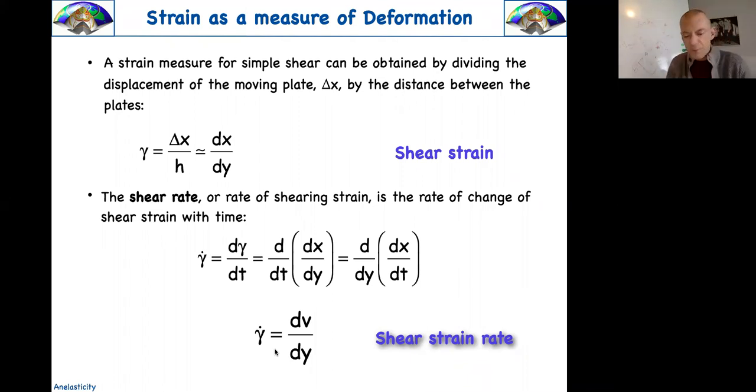You know that moving from seismology to fluid dynamics, the equations of motion are changing. You can use the continuity equation, you can develop the dynamic equations, but instead of being the elastic equations, like for seismology, you're going to build the Navier-Stokes equation, for example, in fluid dynamics. And for those equations, the key quantity is no more the displacement, but it is velocity. And the velocity profile that you're going to create when you're pulling a viscous fluid is deciding its history. So we're moving from displacement to velocity and from shear strain to shear strain rate. And that's the time factor that we will need later.